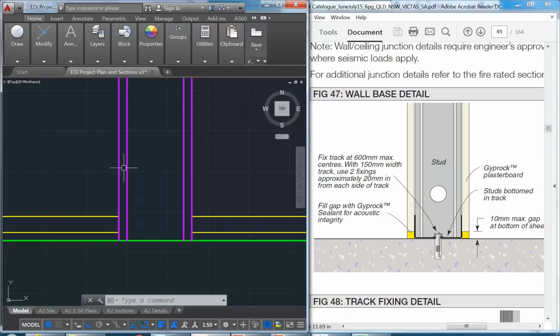The toilet I always do specify for residential these days is one that has a cistern that fits into a stud wall. The whole cistern, as well as the pipe. So for those, I actually do double studs and have them offset and make it a 150 wall, just to give a bit of extra room. But I think you can go down to 120. So lots of options there.